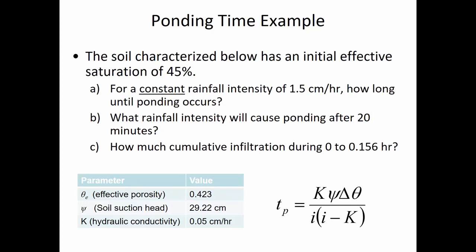And so the total infiltration depth is going to be a little bit less than is predicted by the Green-Ampt method, because the Green-Ampt method assumes that from the beginning of the storm, there is ponding at the surface. But what this shows is that you don't have instantaneous ponding. And so one of the limitations of the Green-Ampt method, remember we talked about it's assuming that there is this constant block wave of going from initial moisture content to fully saturated. And because of that assumption, it's going to be a little bit inaccurate.